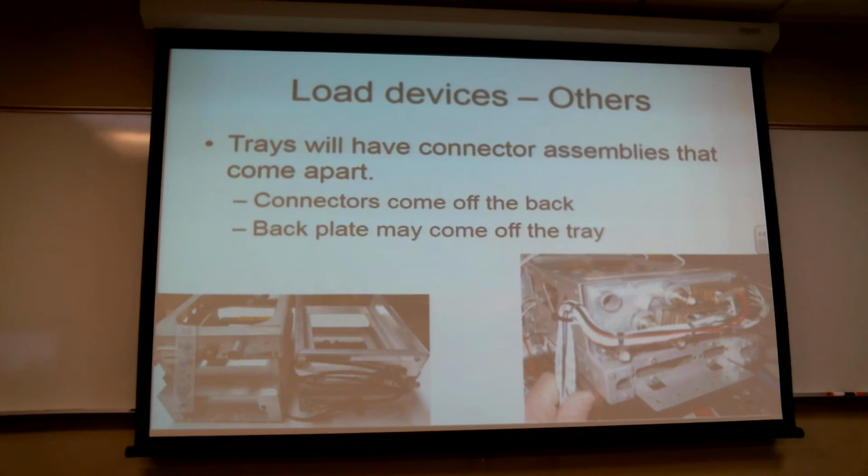Or in this case, you can remove the whole back plate from this assembly so that now the trays are out of the way. You've already pulled the radios out. The radios pop right out. Like a 7/64 or smaller Allen wrench, 5/32. Allen wrench pops them out.